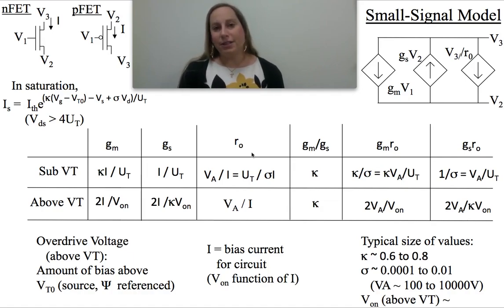But the simple comment to understand is that when you do small signal modeling, you're doing two things. And there have to be two things that you always have to be thinking about. One, you always have to remember that you are removing the DC out of the system. And I can't tell you the number of times I've seen a student look at a problem and then try to immediately simulate or build it and assume that the DC is zero, and nothing works, and wonders, my gosh, something's completely wrong. The answer is yeah, because you forgot your biasing terms. I guess it's a fair comment to say that we all have to be biased to work well, so that's probably a good thing to learn both in circuits and probably in life too.